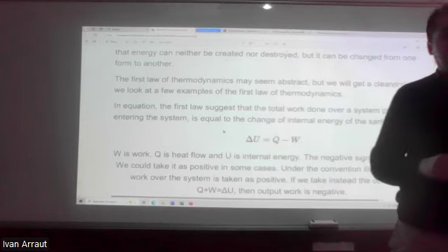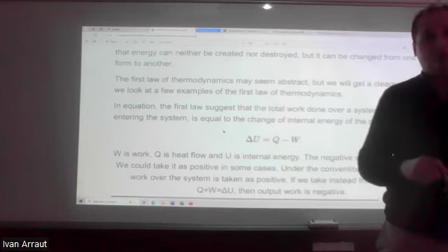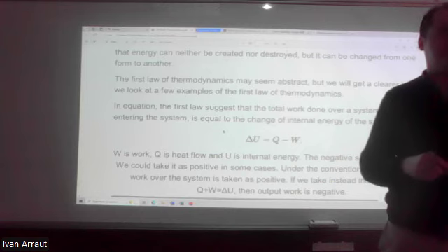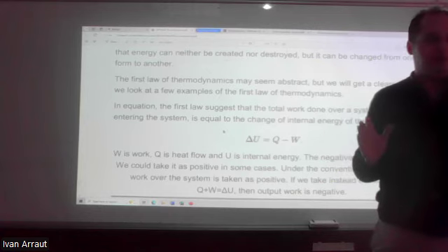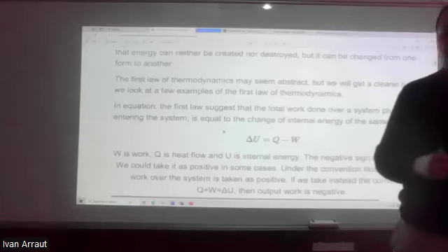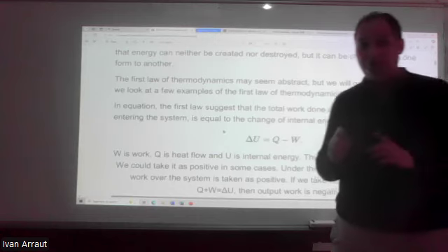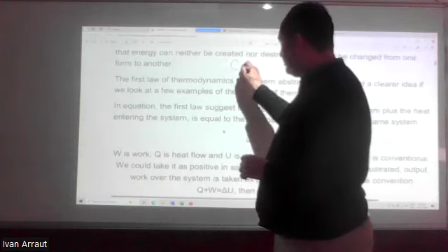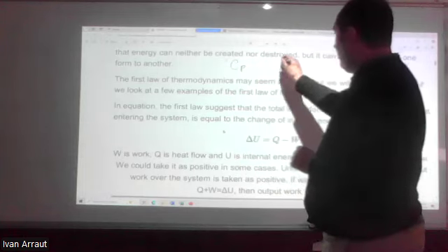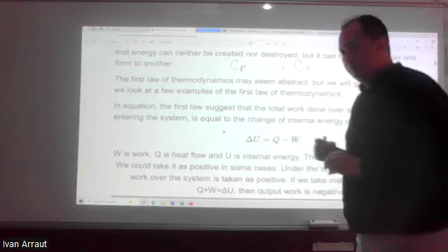So the heat capacity of gases, also with similar formulas, but there is an issue. While for an incompressible substance, there is no difference between the processes at constant pressure or constant volume, for the gases, it matters. So for the gases, you define two heat capacities: one heat capacity at constant pressure and one heat capacity at constant volume.